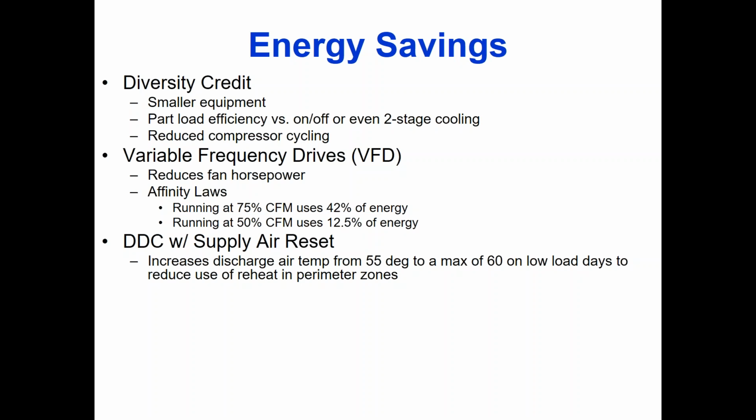There are some things that we can do that are helping us from a control standpoint, a comfort standpoint, and an energy code compliance standpoint. Supply temperature reset is one of those things. If you have DDC controls, then this is required by the International Energy Conservation Code, both the version we use in Wisconsin and the version in Illinois. You have to do supply reset if you have DDC. If you don't have DDC, you don't have to do it because it's pretty much impossible to do this on pneumatics.